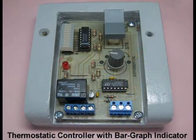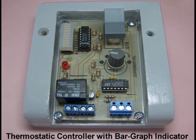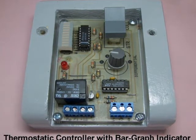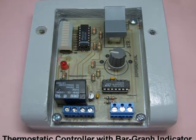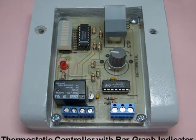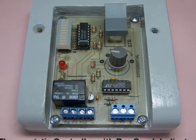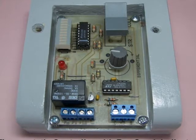This differential controller uses two thermistors to sense a difference in temperature. It also uses a thermistor resistor voltage divider network to generate a bar graph display to approximate the temperature of both the collector and storage temperature.